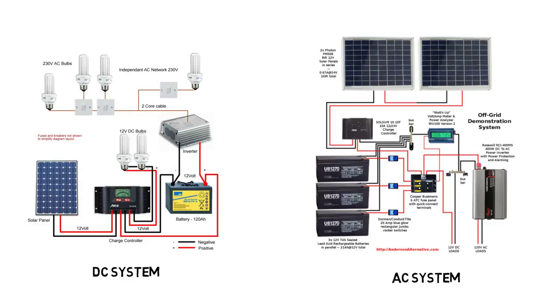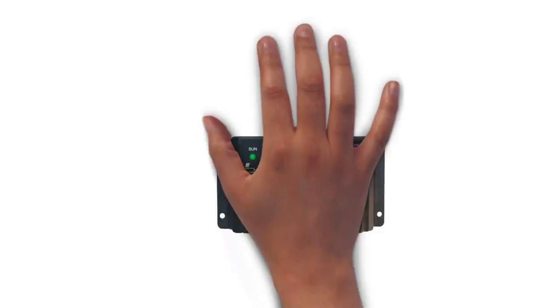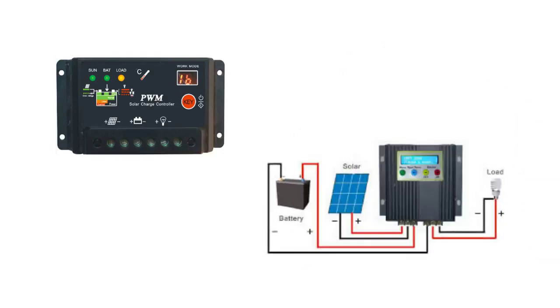There's another important element called the charge controller, as can be seen in the circuit diagram. A charge controller is important to battery health. It should be noted that battery life can be reduced if it's overcharged or when it's utilized if the charge is low. So if the battery is overcharged or undercharged, it loses life. And a charge controller is there to protect the battery from exactly that. The battery shouldn't be drained completely. If it is drained fully, then the number of charge cycles the battery can be used for gets reduced.